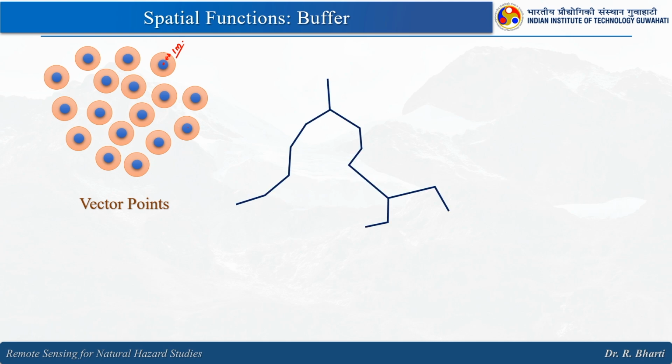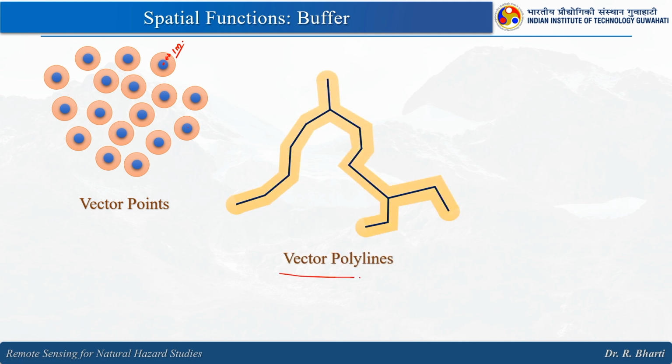Here this is a road network, right, or maybe you can consider this as a river system, and we want to know how much area will be affected by this river, right. Or maybe we want to know, this is a single lane road and we are trying to convert this to 6 lanes, how much area we have to acquire for this particular process. So, in such cases what will we do? We will just run the buffer, so buffer of the polygons or the polylines.